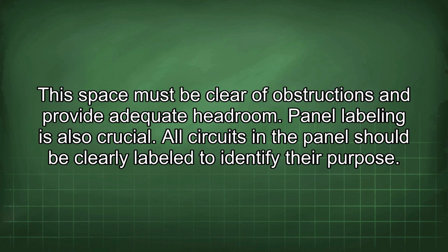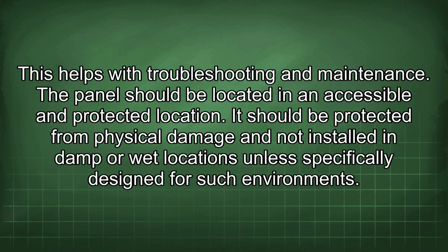Panel labeling is also crucial. All circuits in the panel should be clearly labeled to identify their purpose. This helps with troubleshooting and maintenance.